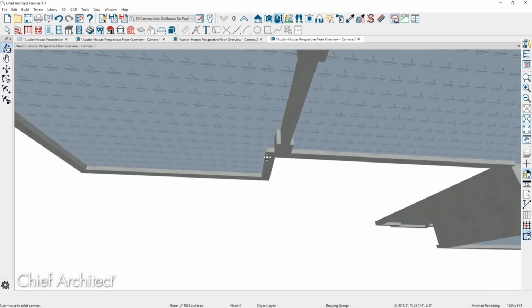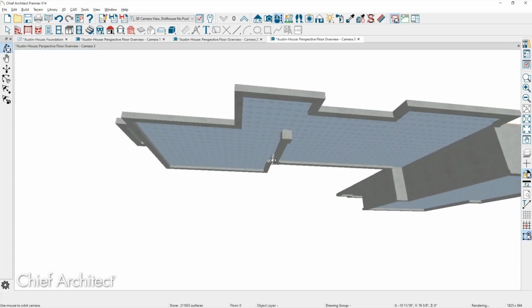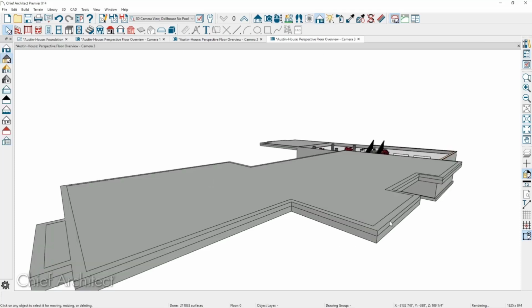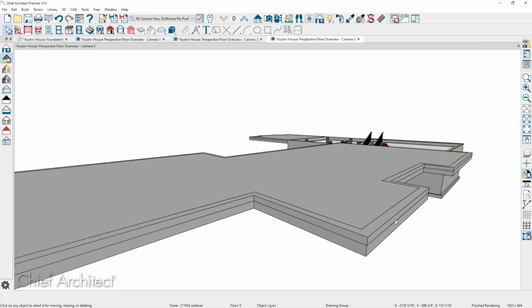Well, let me help you out here, because I think this is where the problem comes in. I've got a 1-foot stem wall on top of my footing. So your picture doesn't work, because the footing's actually down 12 inches from a stem wall. Okay, so your stem wall is popping up 1 inch above here, right? No, it's at the bottom of the slab, because the slab sits on top of the stem wall, or flush with it. But my minimum stem wall is 12 inches.